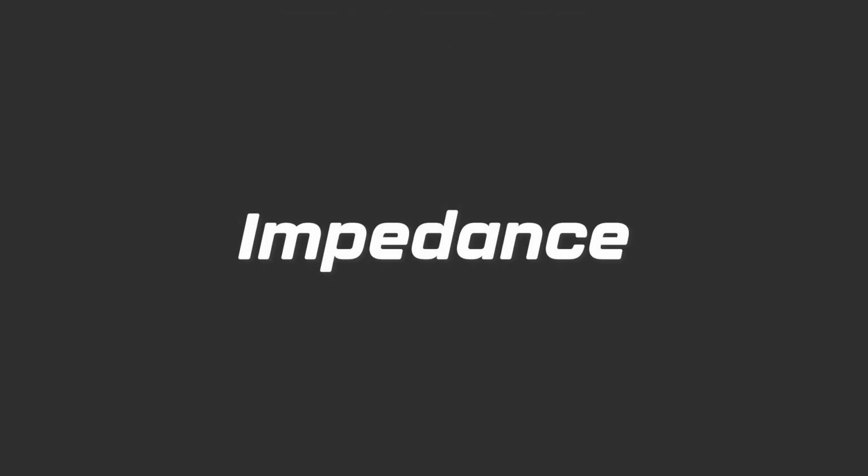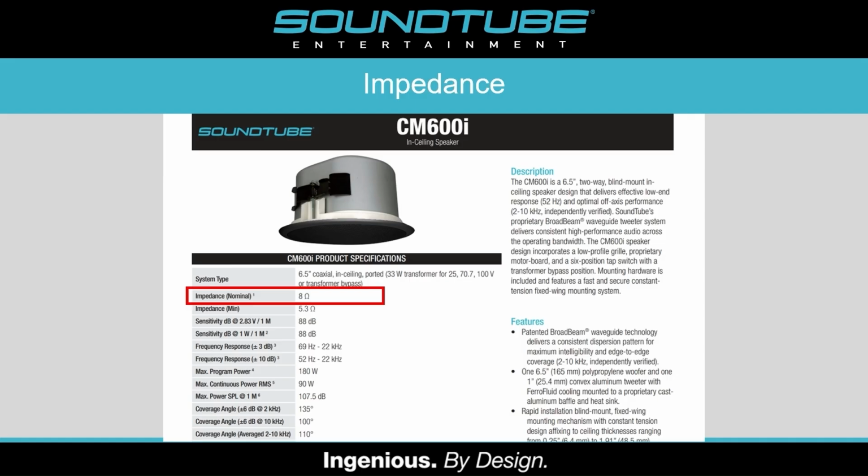Moving top to bottom, we are going to start with the impedance section. The impedance stated in this section is the impedance of the transformer bypass. This means when the speaker is not being used in constant voltage mode, the impedance is 8 ohms. Without diving too deep into electrical engineering, this rating is used to calculate the resistance on an analog speaker line.